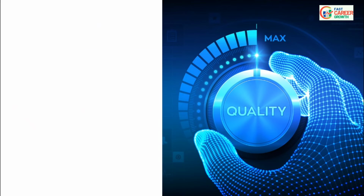Next is Step 9. Quality maintenance. Quality maintenance is a core pillar of TPM, and its focus is on ensuring high product quality, reducing defects, and minimizing variations. It's a proactive approach aimed at maintaining equipment to prevent errors and inconsistencies in our products. Key components of quality maintenance include preventive measures like regular inspections and calibrations, as well as root cause analysis to identify and eliminate the sources of defects.